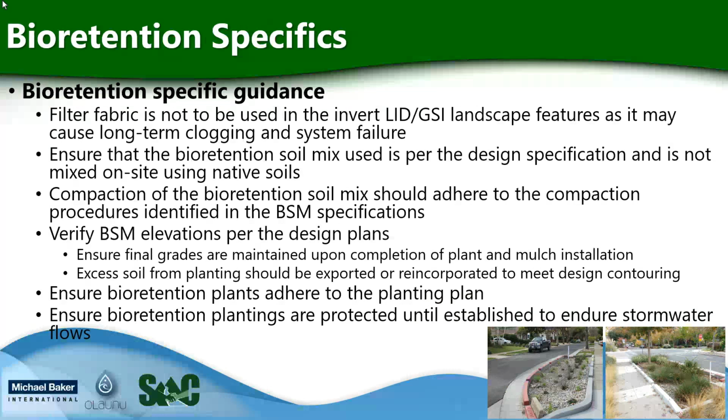There should also be a verification of the BSM elevations per the design plans. We want to ensure that the final grades are maintained upon completion of plant and mulch installation. And excess soil from the planting should be exported or reincorporated to meet the design contour. It's critical. We see a lot of systems where they put in too much BSM, and that reduces the capacity of the system. We also want to ensure that the bioretention plants adhere to the planting plan within the design submittal, and that the bioretention plantings themselves are protected until they are established to be able to handle the velocity of stormwater flows into that system.